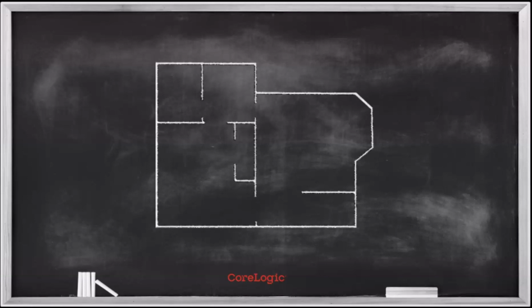The other reason in looking at a floor plan like this that I might establish a separate drying chamber is if I have very, very unique and critical needs in one area versus another, right? So, and I may look at it this way, for example, maybe this larger room right here, maybe that area is all hardwood flooring, and maybe it's a really high value hardwood flooring. Maybe it's some Brazilian hardwood or something like that, and there's a lot of value per square foot in that floor, and I need to get on it quickly and address it much more aggressively than I would the balance of the space.